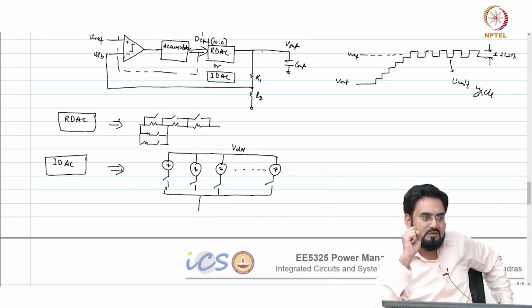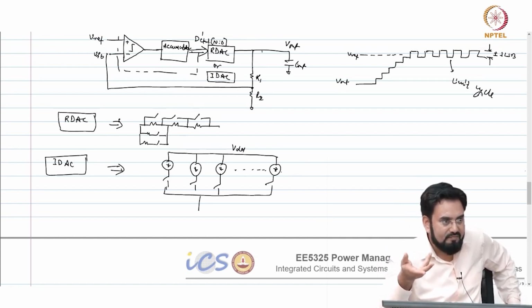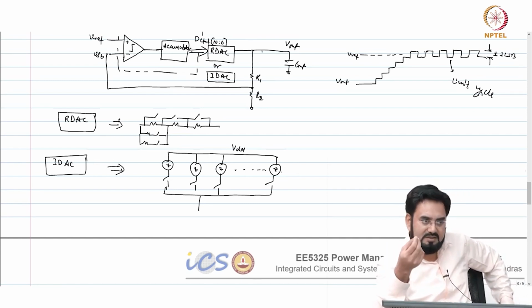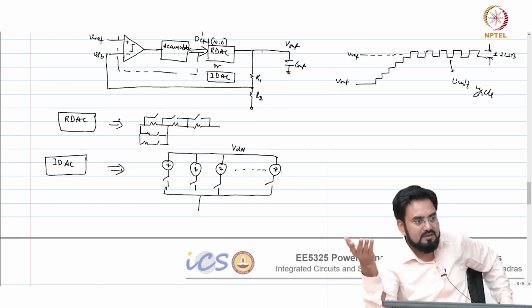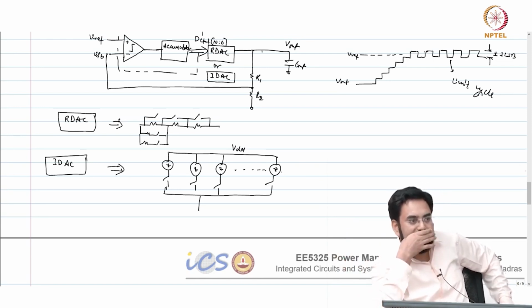Okay. So, your LSB, the accuracy will be decided by the highest value resistor you are choosing, that will define your LSB size, the highest value resistor. Okay, because that will cause a minimum change in the current. So, then you have to decide what will be the resistor based on your lightest load. When you go to the highest load, that resolution will further improve. Okay.